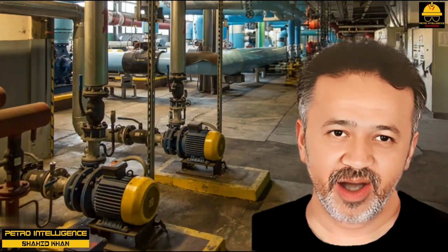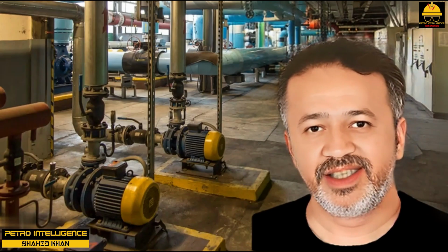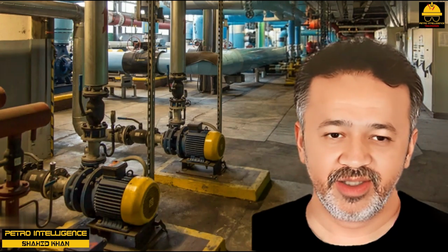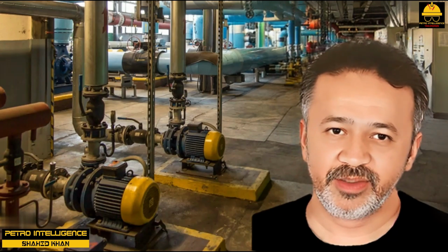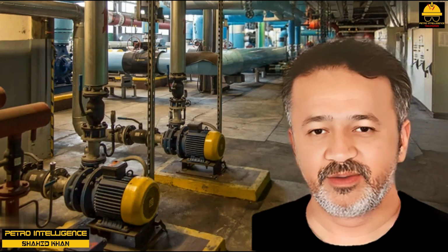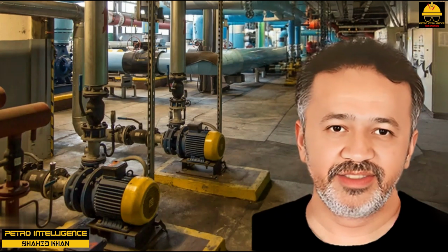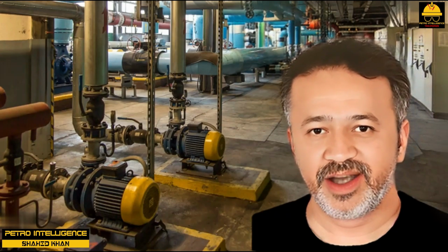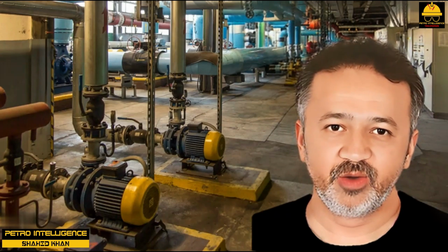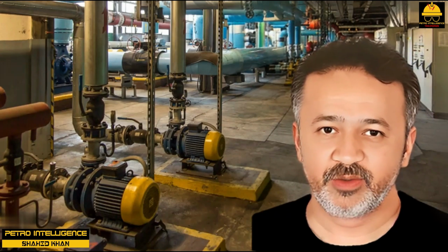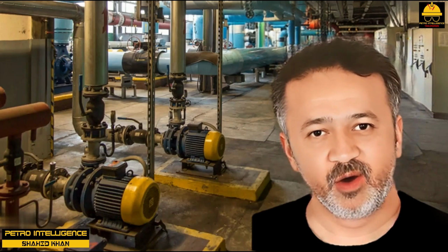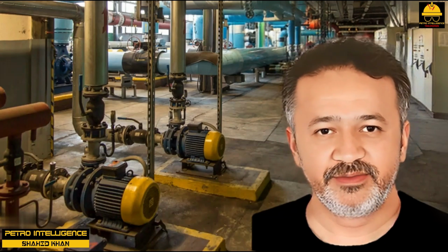Gears. On occasion, pumps are not directly connected to either a motor or a turbine. There is an intervening gear, which can increase the pump speed by multiplying the driver's speed. The gear is another source of possible misalignment and vibration. I have always considered such reduction or speed increaser gears to represent poor design practice, and an unnecessary complication as they often require their own lubrication system.